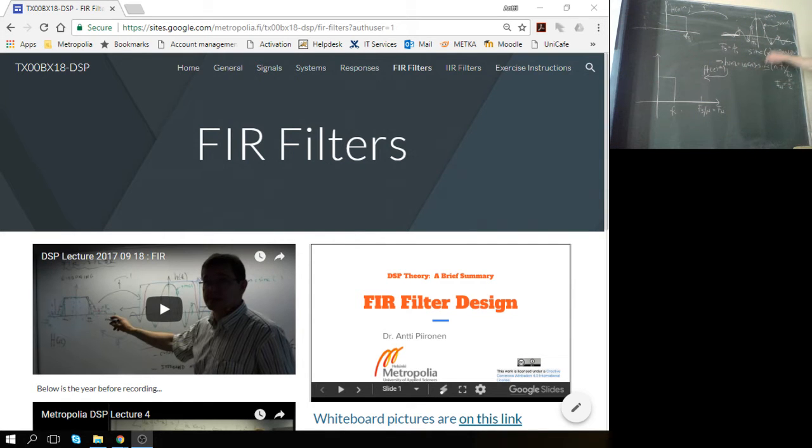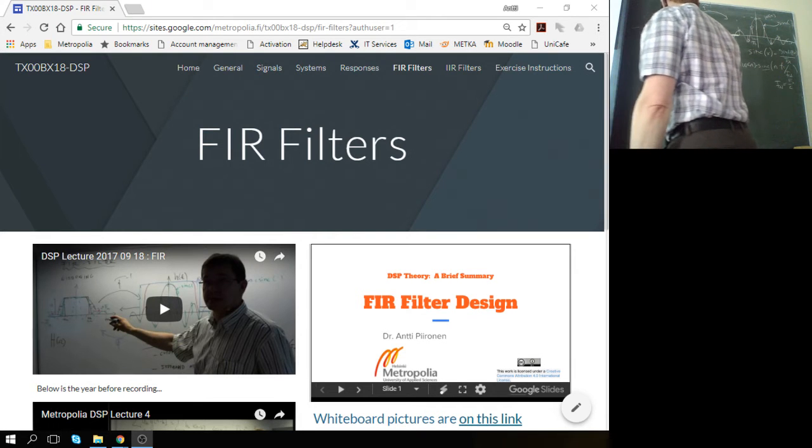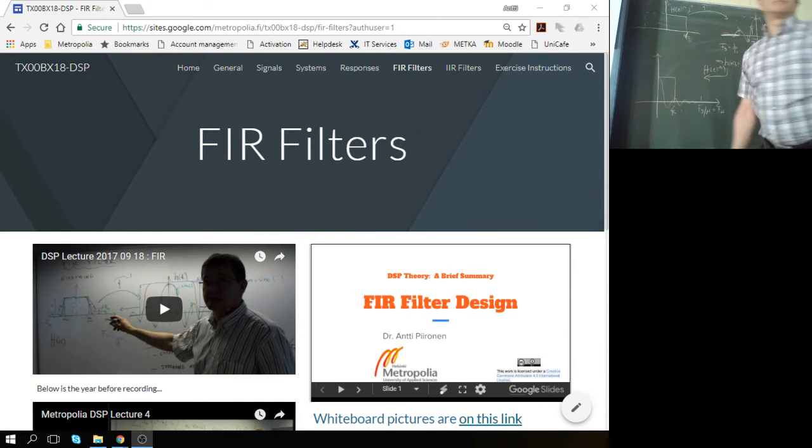But on the time scale we multiplied it with a box. The Fourier transform of a box is the same as the inverse Fourier transform of the box, which is a sinc function, but this time the sinc function is on frequency space. All right, so we have the sinc function here.